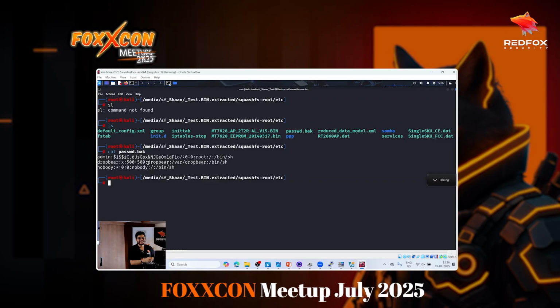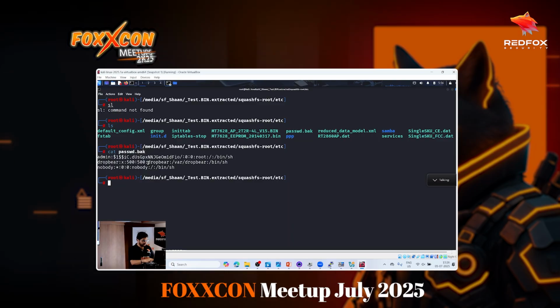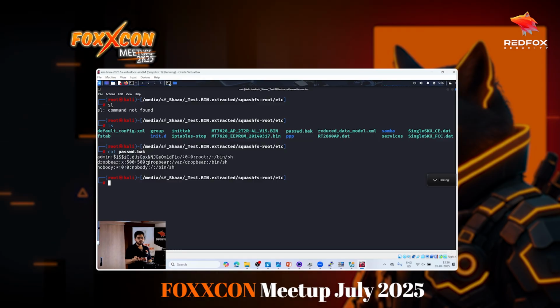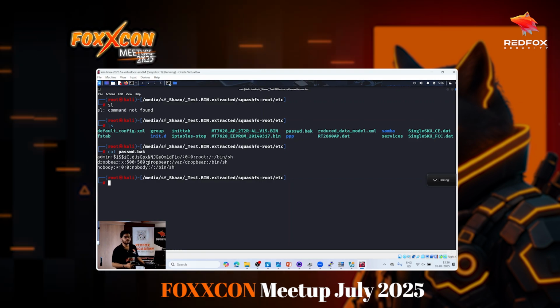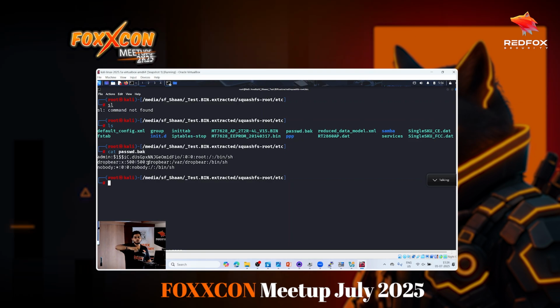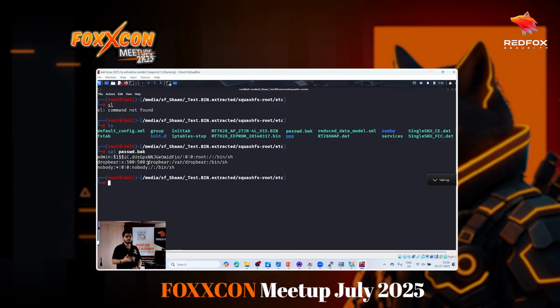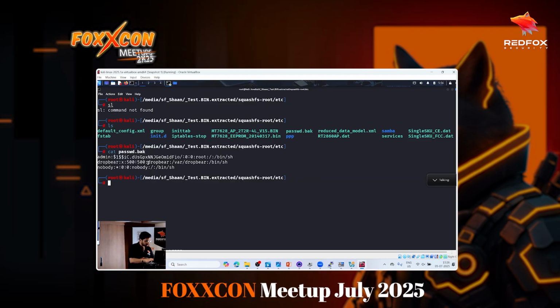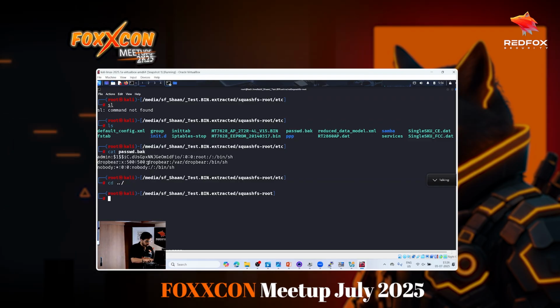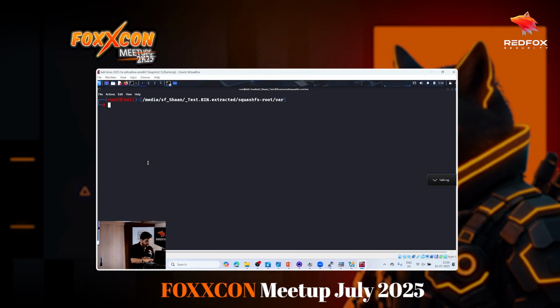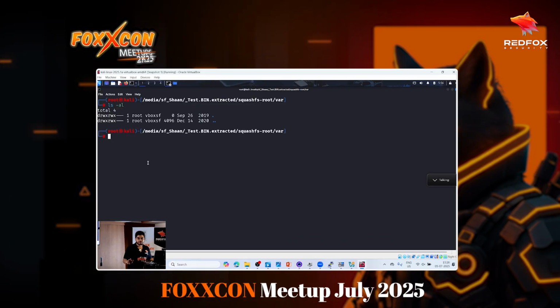It is 1234. One thing that is different in terms of why we do something like this rather than just the shell over UART: the shell over anything that is running is important. Why? Because all the kernel loading things will be done after the fact. When the system is running, that is when you will be able to do dynamic analysis and see what the file system looks like after booting up. Like now, if I go into var, there will be nothing there. See, var is empty.